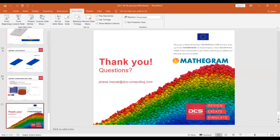Yep, very good. Philip Cardiff is asking, would it be possible to include particle melting to simulate laser beam powder bed fusion? Of course. To really make this useful, we would need to include melting, because as I showed in the example, if we don't include melting, the temperatures go too high compared to what they would be in nature. So the next step would be to couple it together with melting, with phase change.